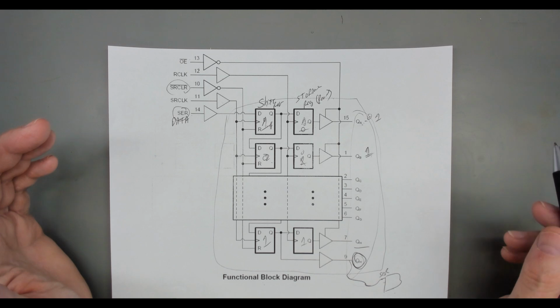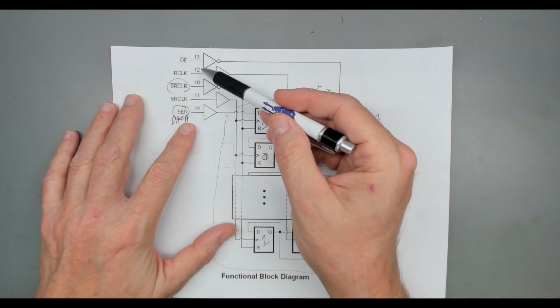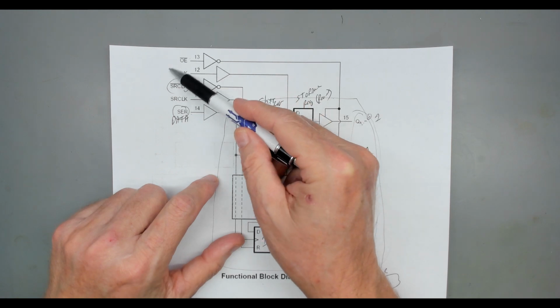Like I said, a few caveats. There's a couple caveats actually. It's how long it takes to load, and you can get so many chips that your microcontroller has a hard time driving the lines. But then you put a buffer chip on there, and you can solve that very easily. With that, that's what this chip does, and that's going to be the end of this video.